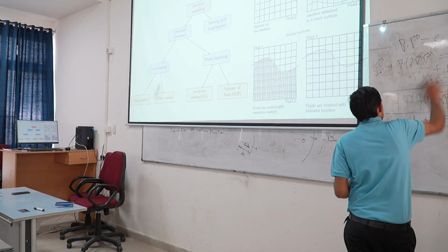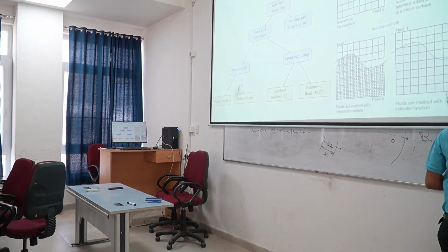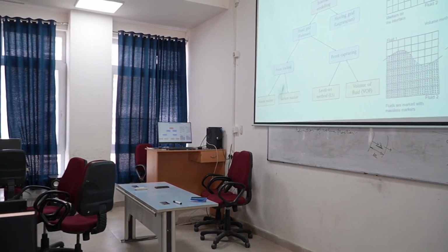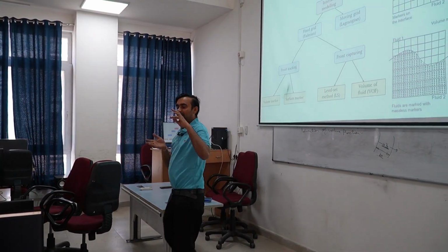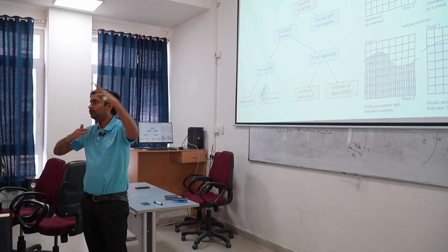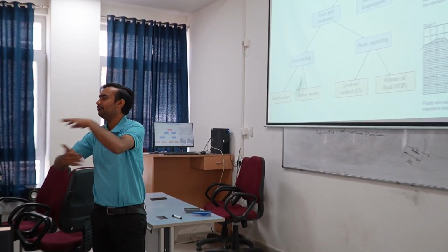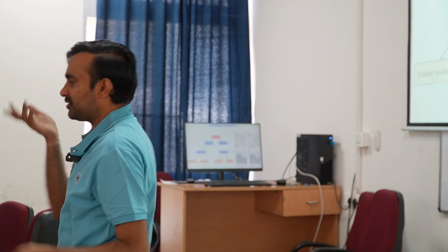After the governing equations, you have to also understand one point: whenever this volume fraction advection equation changes the volume fraction field, in each and every cell a new value of the volume fraction will come up. What we need to do with that?